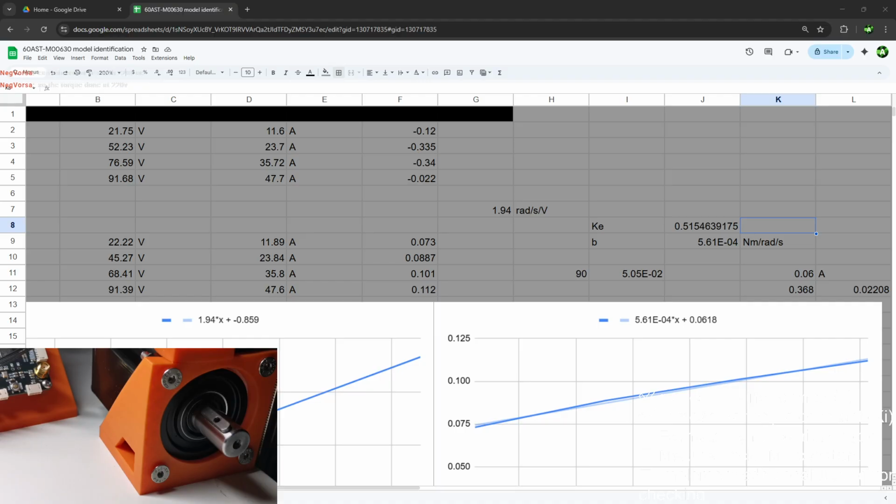So the torque, it doesn't matter. Your torque is directly proportional to your current, always. There is absolutely nothing in the world that can change it unless you have a saturation in your magnets, unless you hit a non-linearity limit. So you can measure it at 10 volts as well. You can measure it at 1 volt, but at 1 volt you will have too much friction interfering with the measurement. What is important is current, and current is proportional to voltage and resistance, and it doesn't matter at what voltage you achieve this current.